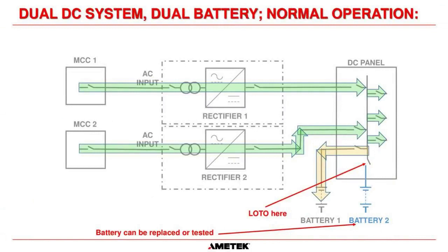Okay. Now, the other great design of this, obviously, batteries have to be tested on a regular basis. IEEE 450 and all the other applicable standards apply. And if you have a wet cell battery, usually you're going to have to do a capacity test on that battery every 4 to 5 years. That's a maximum duration. Sometimes you have to bring it in a lot closer than that. And plants may have their own routines that they go through, but you are going to have to capacity test a battery every 4 to 5 years.